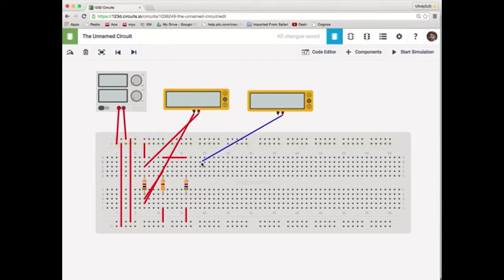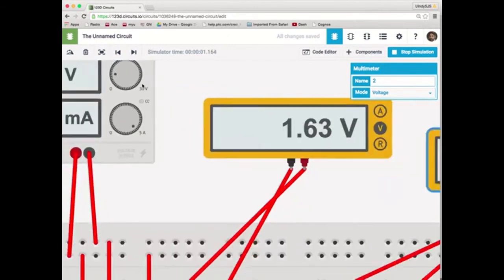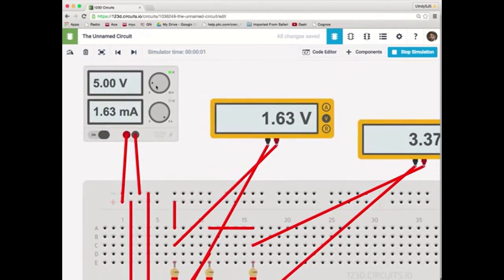5.6K. This is exactly how you do it in the lab when you connect a multimeter to a circuit. You take the positive terminal and connect it to the high potential, the negative terminal connect to the low potential, and you make your measurement that way. So let's go ahead and fire that thing up. Now, instructions say we want to run at 10 volts, so I'll zoom in here, dial this guy up to 10 volts. There we go.